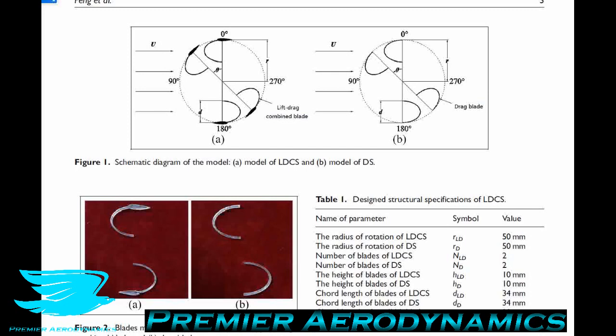Looking at figure 1, we can see that the direction of the lift generated is towards the axis of rotation. We have the airfoil pitched here, the air comes in, and the effective angle of attack means that we get a low pressure zone on here, and that should drive a force towards the axis. We'll see a little bit later what the flow fields look like, and we'll get a better appreciation as to when the airfoils are producing lift and under what conditions.